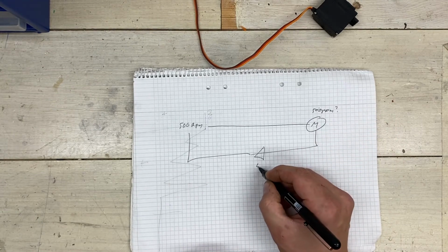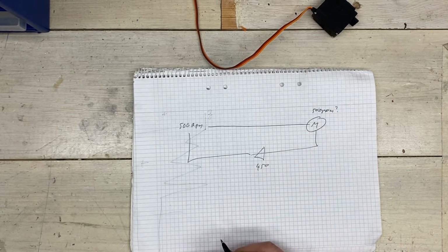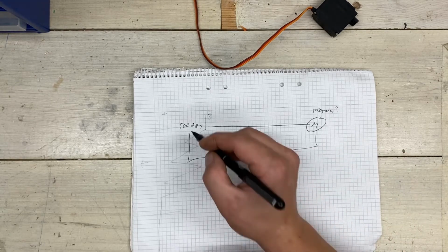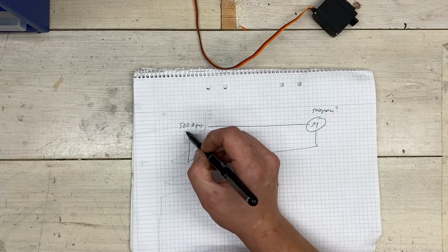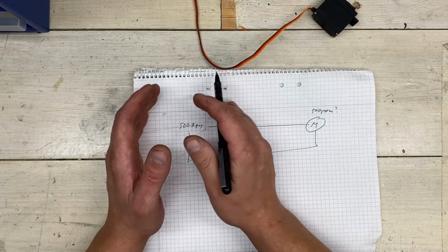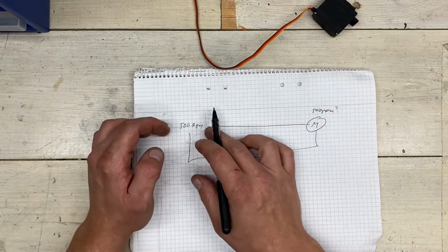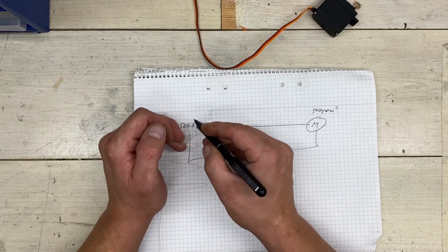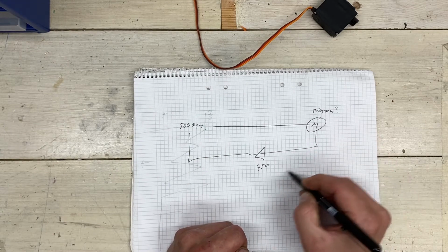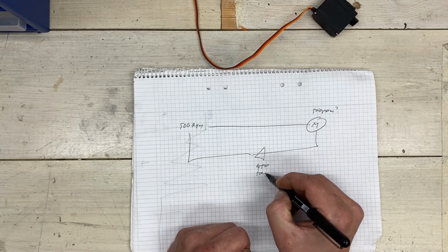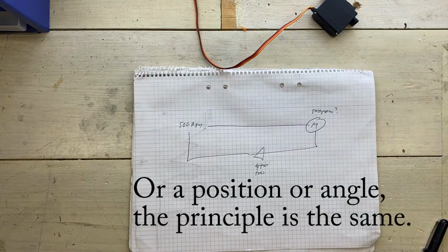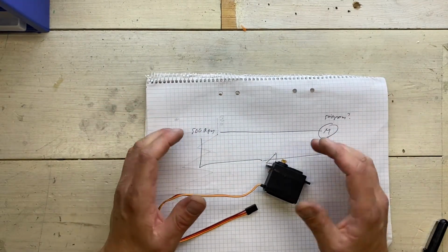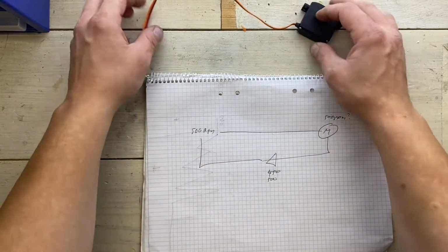And the signal it sends is the current speed. And if this speed is, let's say, 450, even though we told the controller that we wanted the motor to go at 500 RPM, the controller will keep increasing this signal. And of course, we're not telling the motor to go RPM, we're simply sending a reference, usually voltage or current. And this voltage or current will continue to be increased until this feedback signal reaches 500. And this is a servo system. And now I'm going to show you how we accomplish this in an RC servo.